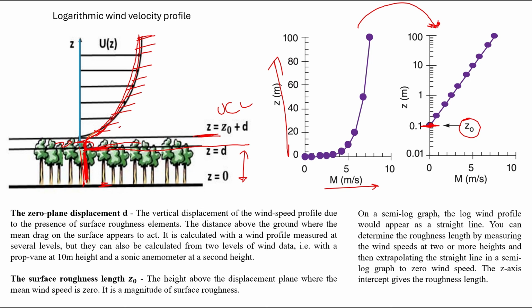But measuring the velocity at so many points is very difficult. So normally they measure the velocity at just two points. One is somewhere above 10 meters, and then another one near that. They take just two points, join them, and project the line to the zero point. With that they measure Z0. Finding all the points is also possible, but it takes much resource and time.